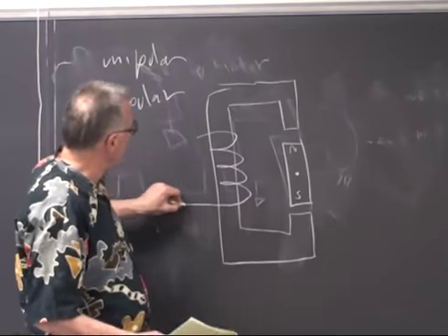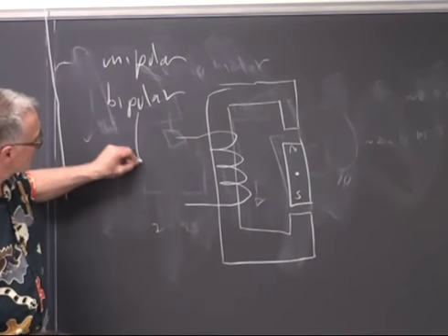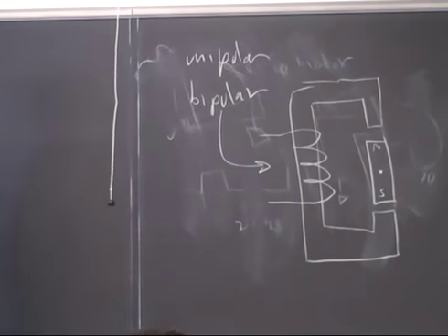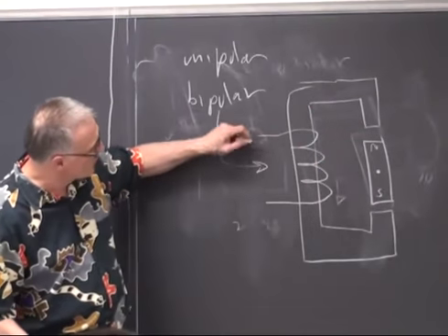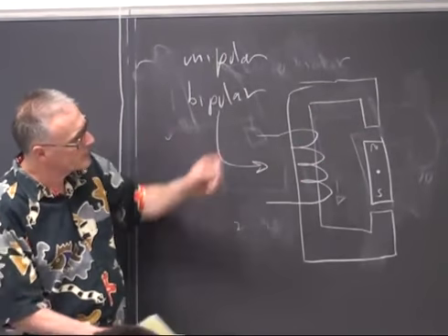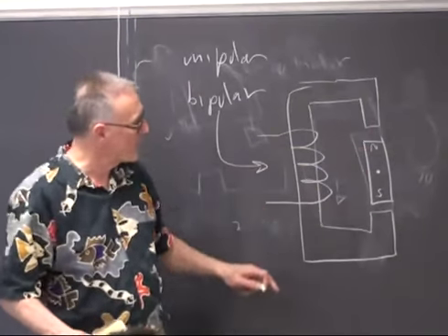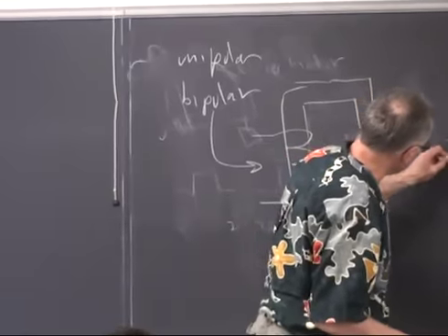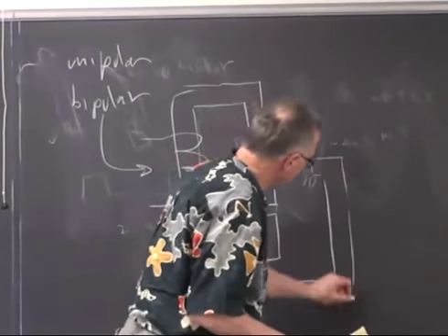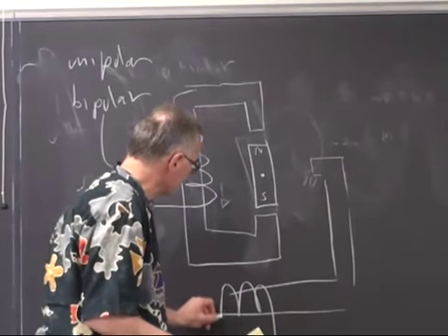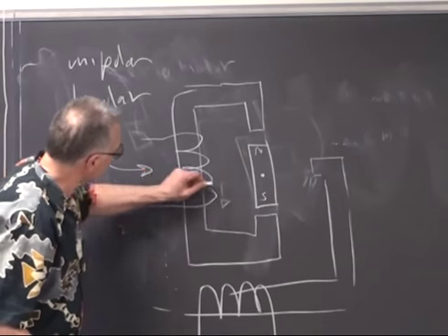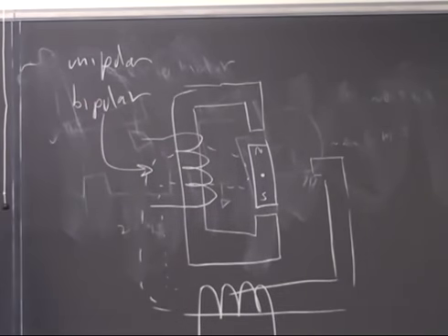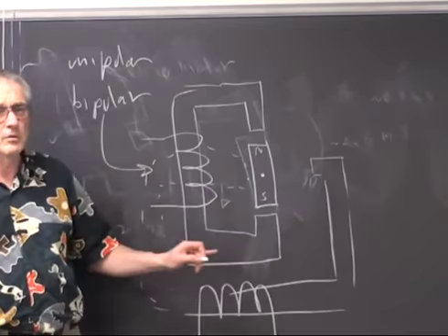And in the case of a bipolar motor, there is a coil around that's actuated either with current going this way through it or this way through it to change the polarity of this electromagnet. And then there's another set of pole pieces connected to another coil that is at right angles, and in fact most motors have several sets of poles to get a finer angle than 90 degrees.